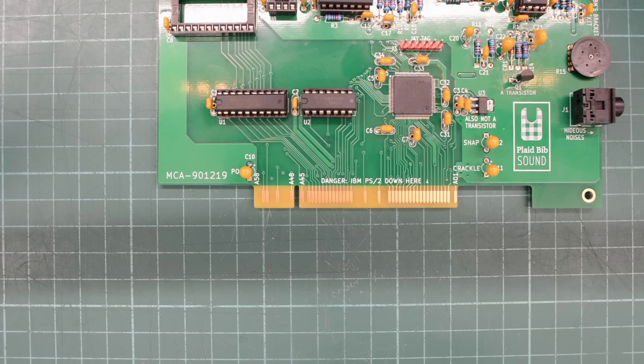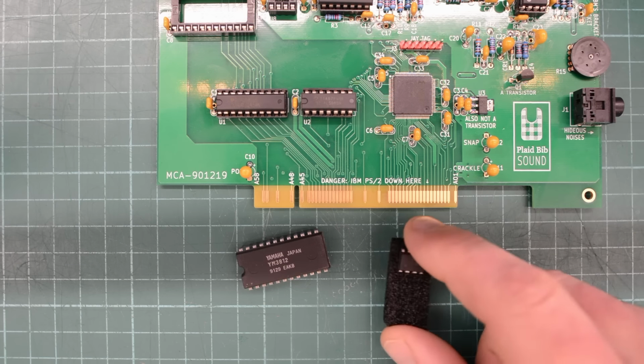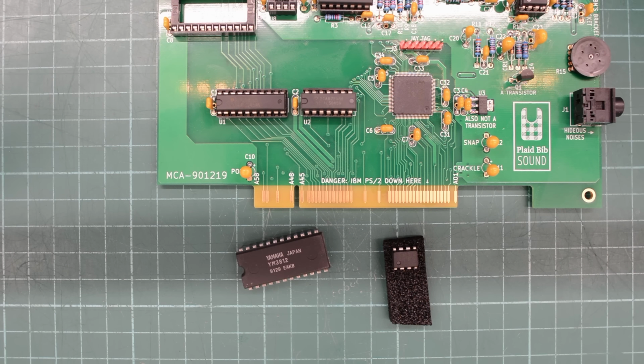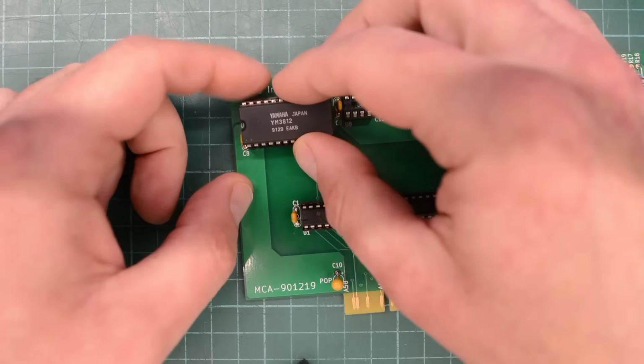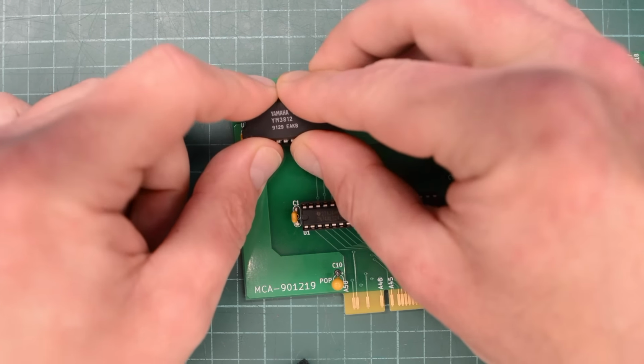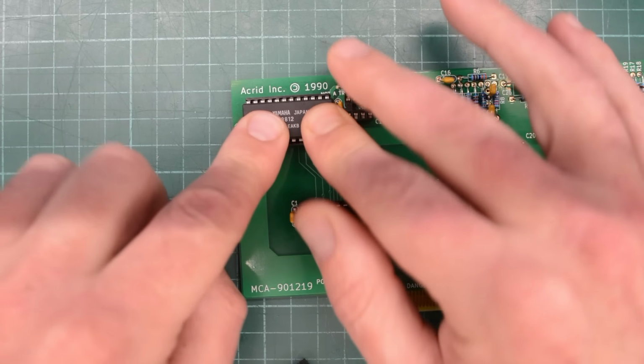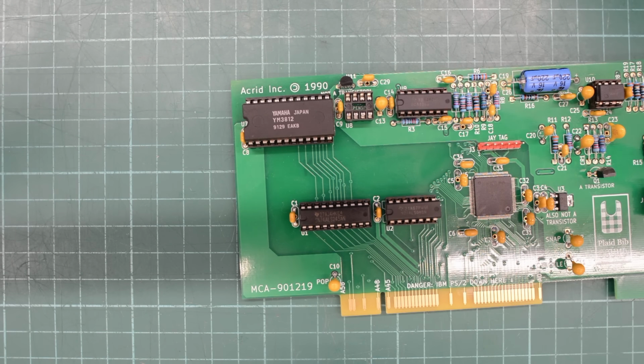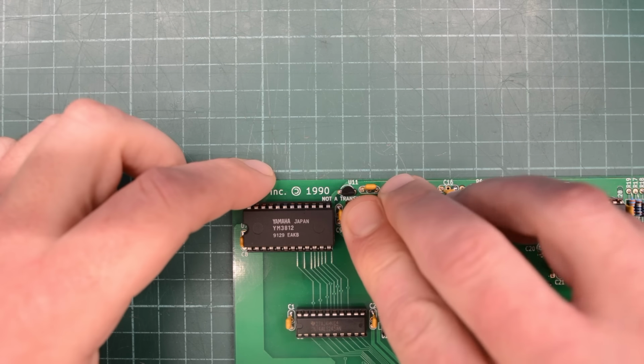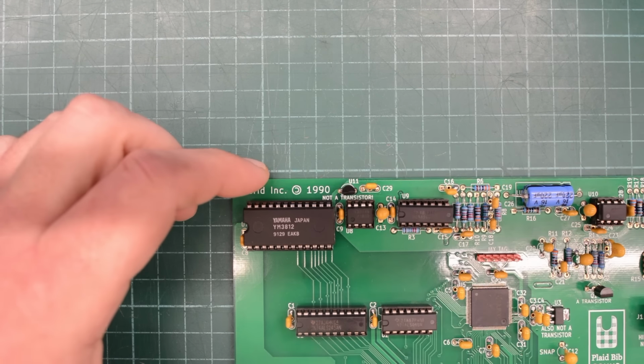All the components we have used so far are available to buy brand new, but there are 3 components that are not. So you're gonna have to source these on eBay or AliExpress. Firstly we have the Yamaha OPL2 chip, the YM3812, and then we also have the DAC, a Yamaha YM3014B. And the third part we are gonna talk about in a second. So let's install these first. They are of course U8 and U7.